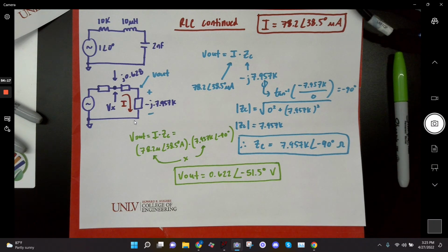If it's more of an inductor, it will be between 0 and 90. Right. Okay, that makes sense. That's what I was curious about. And on the homework, you might have seen the same pattern, that they were 90 degrees apart, but that's because there was a purely capacitive circuit and a purely inductive circuit. There was no mixture of capacitors and inductors.